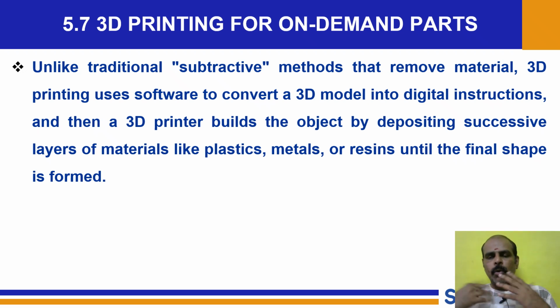The advantage here is we can directly go ahead with the production of hollow parts. There is no conventional process available to produce hollow shafts, especially in a stepped nature. The only way is to remove material from the inside core part and make it hollow. But with 3D printing, the design itself will have the hollow nature, and therefore whatever you have in the design, the same can be manufactured.